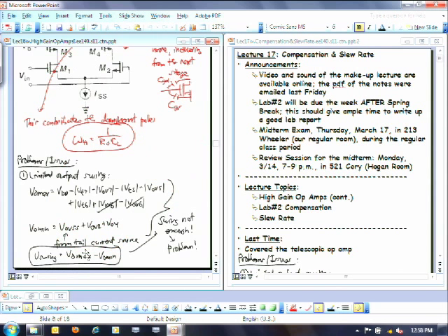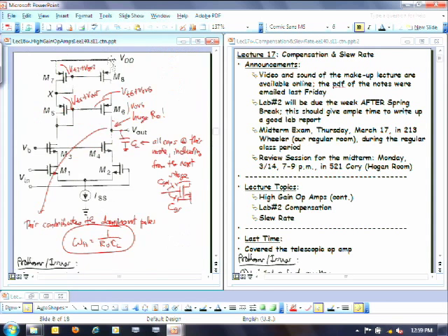But because we had to use so many transistors stacked up, each transistor you use in a stack takes up some of this rail, right? We've got a rail from VDD to ground here. That's the total voltage we have across this. It's supplied by a battery or something. And if we use too many transistors stacked, soon their VOVs or their VGSs added with VOVs will get so large that you barely have any room for an output voltage swing.